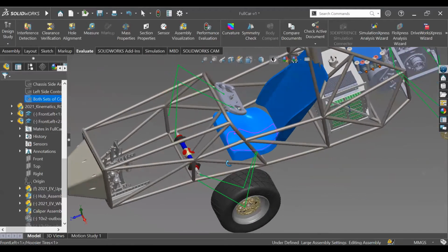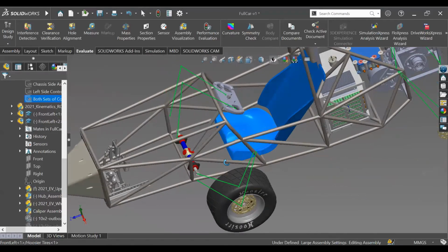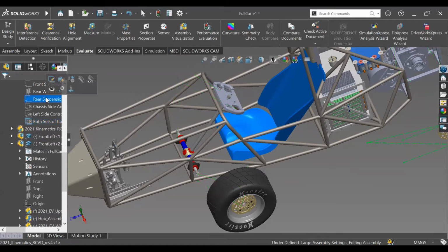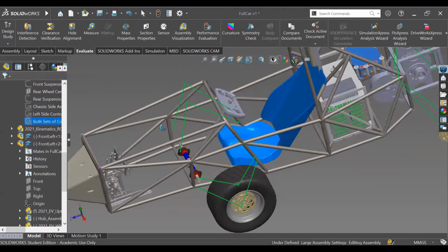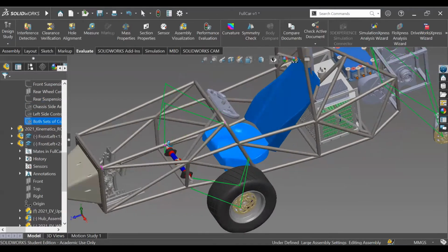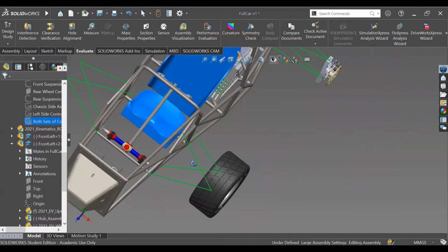Let's start with control arms. We work very closely with the chassis subsystem so that we can work together on its mounting points. So far, we've mapped out these control arms using a bunch of chassis constraints, equations, and mounting points. And then we found out the instantaneous centers to get their shapes right.